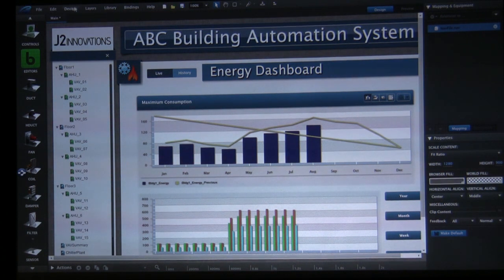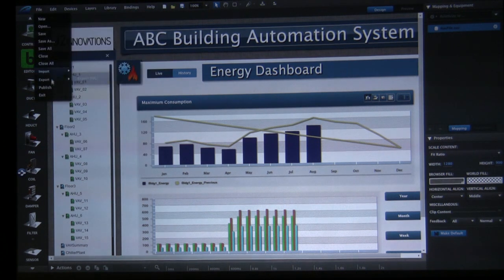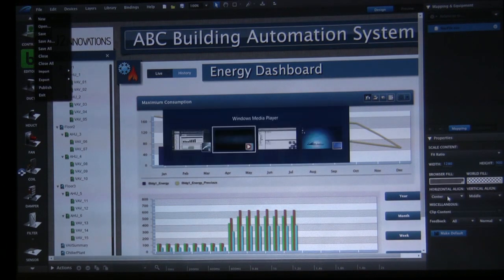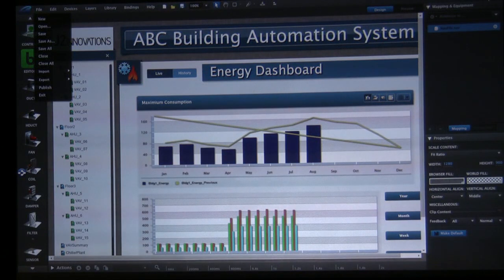The last step that your guys are going to do in class is they're going to come over here and they're going to do what's called publish. And that takes that payload and puts it on the server. So in this case, our current server is the Niagara framework. And so behind the scenes, these all get put into the JACE or the web supervisor as a component in the space, and all the assets get put down in the file system nice and efficiently in that one mouse click. So, yep. And so ultimately, actually, let me just take you through that scenario.